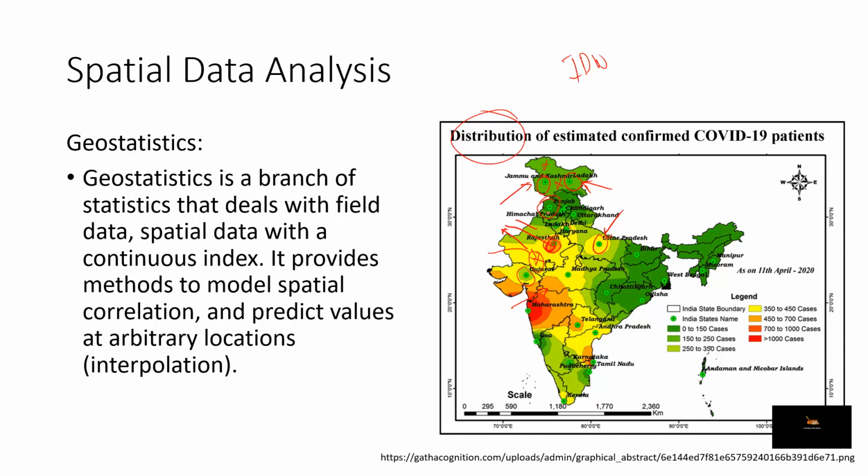Apart from the IDW, one of the most sophisticated interpolations is called kriging interpolation, where you need to have several pieces of information before you run the process. You need to insert the correct information. If not, it will produce less accurate data.